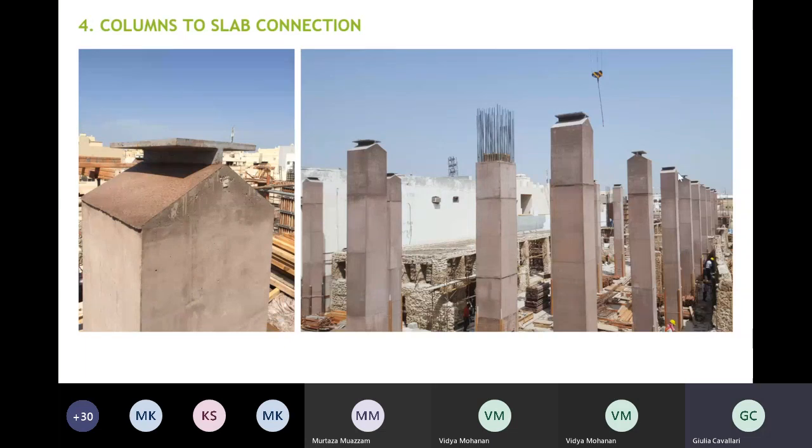So from this picture, we see the taper at the columns gives the roof slab a floating effect, and the orientation, you see here there is a different orientation for the column apex, is a compromise between architectural feature and structural function. So for example, at locations where we had long spans, we couldn't accommodate this direction of the apex, and we had to turn it around, going into discussions with the architect to see how to achieve best the architectural intent.